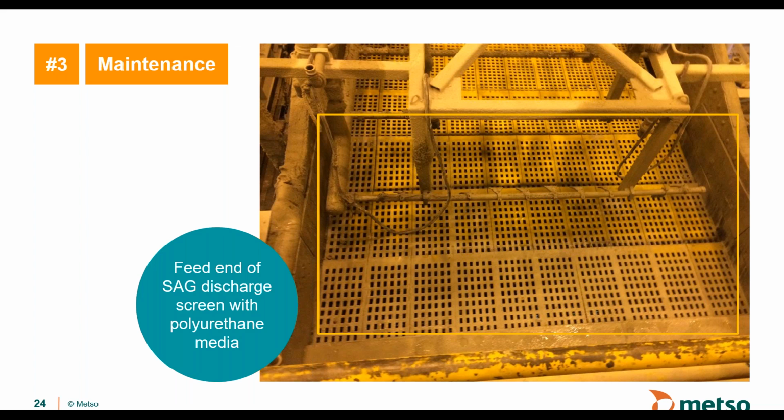That is to handle the bigger material flow, the bigger abrasion, anything that comes with a feed that goes quickly down to the screen, like you can see here. That is also a way of prolonging the wear life of the screen deck without putting in too much blank area to reduce the capacity. You can have different setups in the feed end and in the remaining section of the screen to balance the life of the screen.